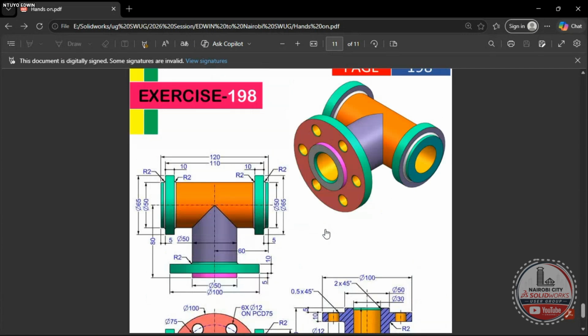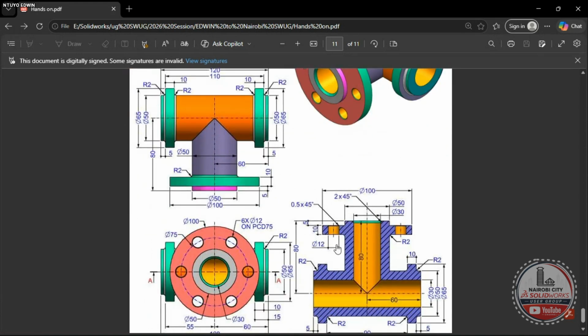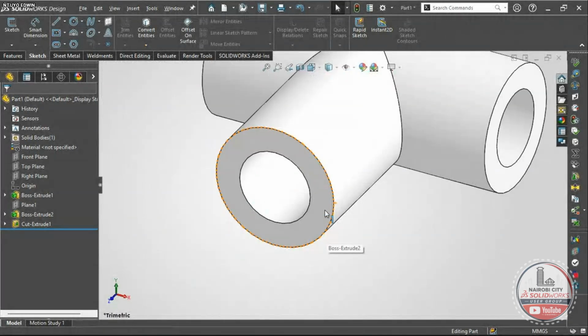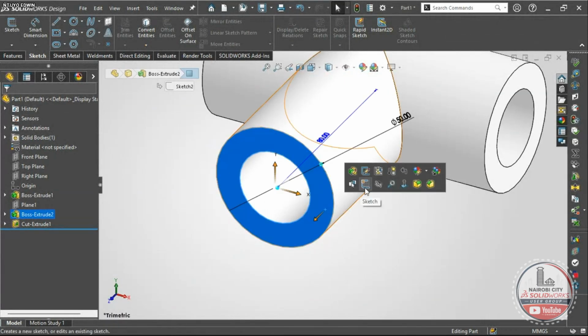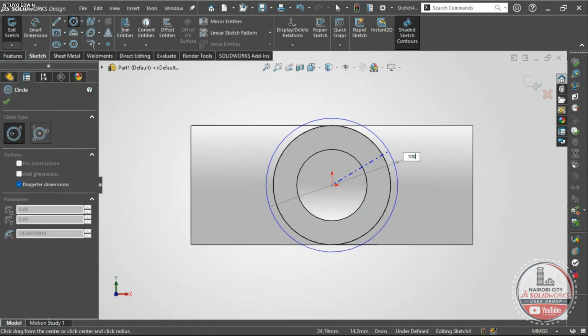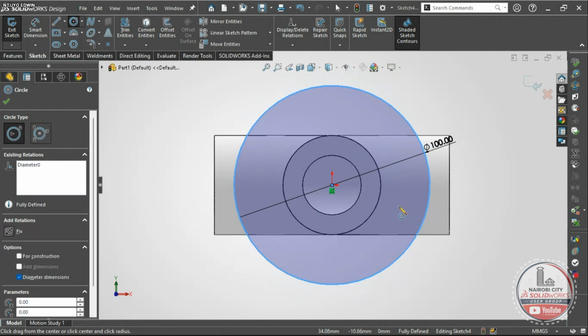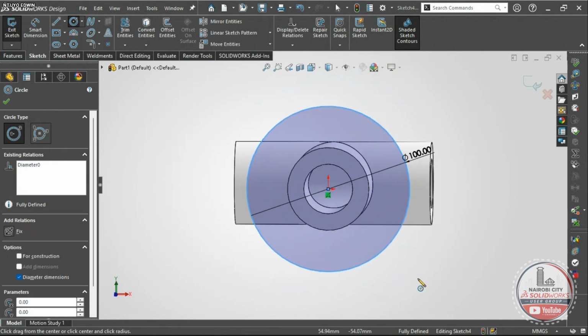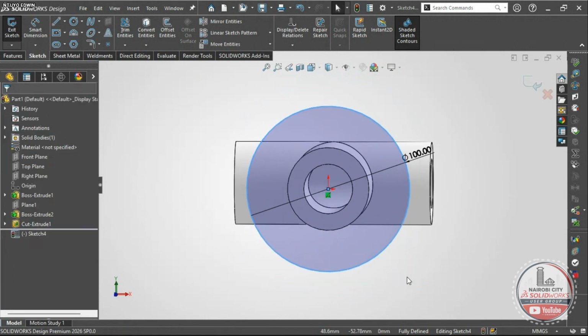So you find that now I'm first going to draw onto this extension that I have drawn up. And when you come onto my section, you find that this extension here is of 100 millimeter diameter. So I'm going to go back to my software. I choose this, I say sketch, and now I'm going to draw here something of 100 diameter. Okay, this is the one I have.